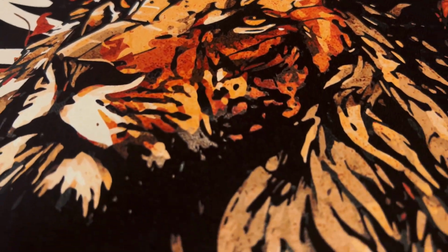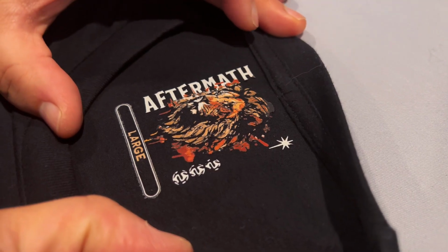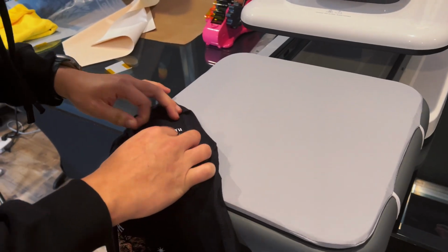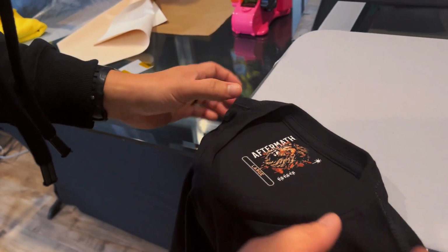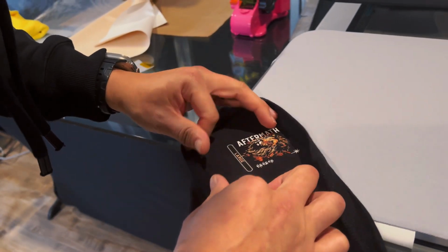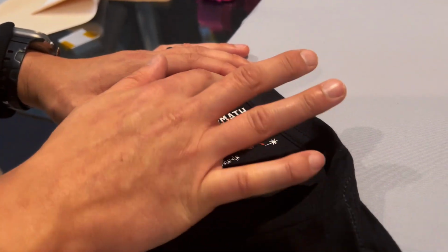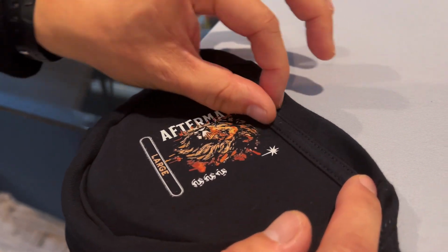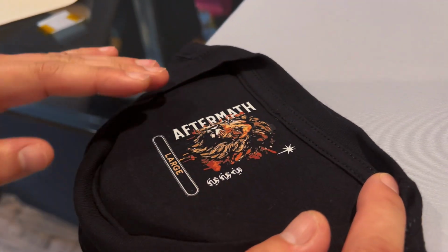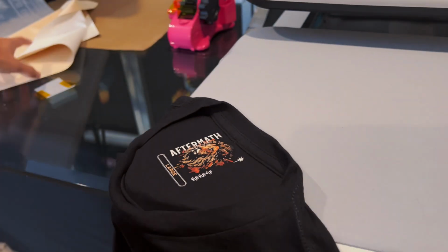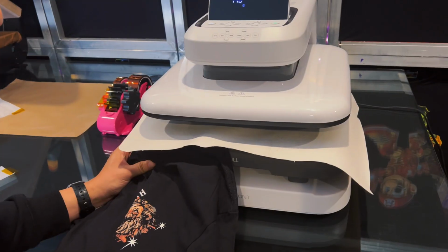All right, let's go ahead and hit the neck tag. We'll finish it off there. So let's go to press it one more time. Now, what I would normally recommend doing is putting a heat press pillow underneath here. That way, this is gonna be flatter and you're gonna have a better surface to press at. Because right now, you're dealing with this neck seam right here. This gives it an elevation, and so the top part right here is not gonna adhere as well as if you had a heat press pillow. So let's just go ahead and do a second press. We can use our matte sheet here, but I'm gonna show you what I'll do afterwards.